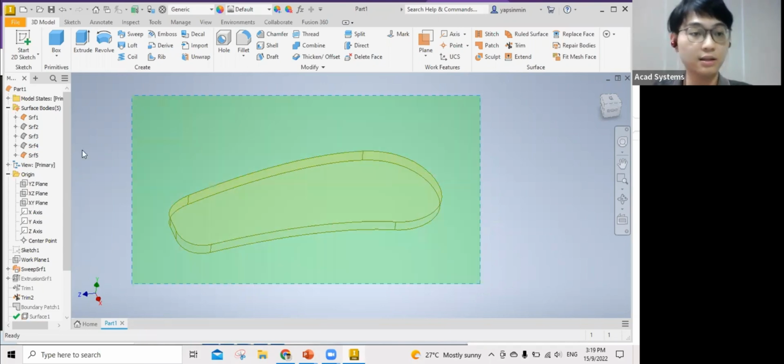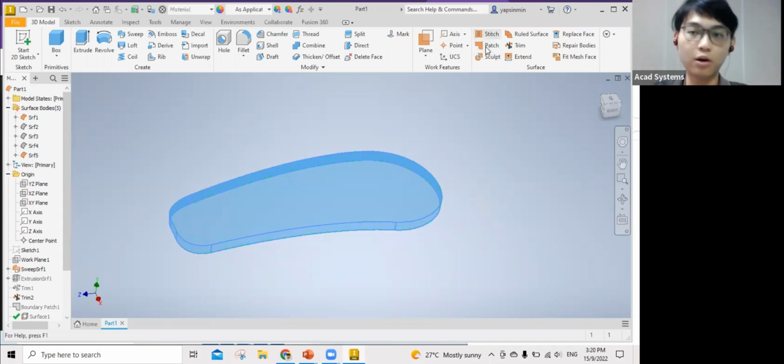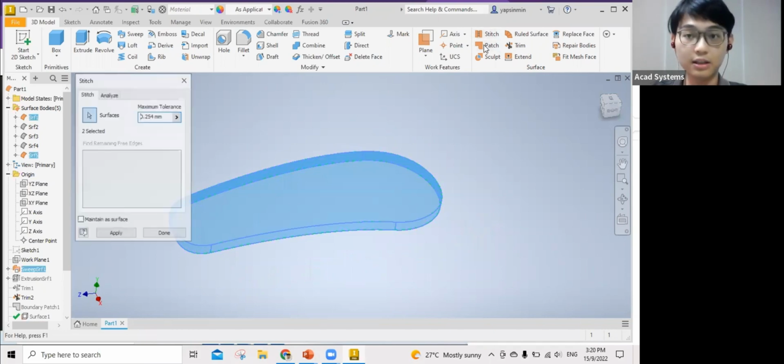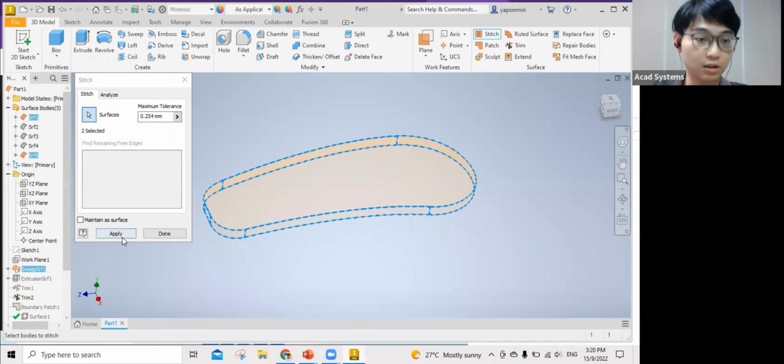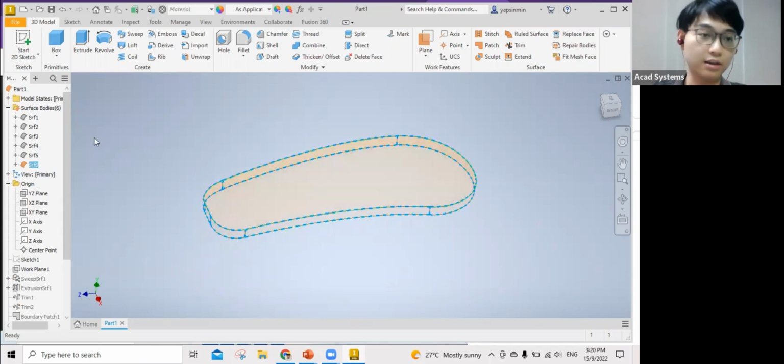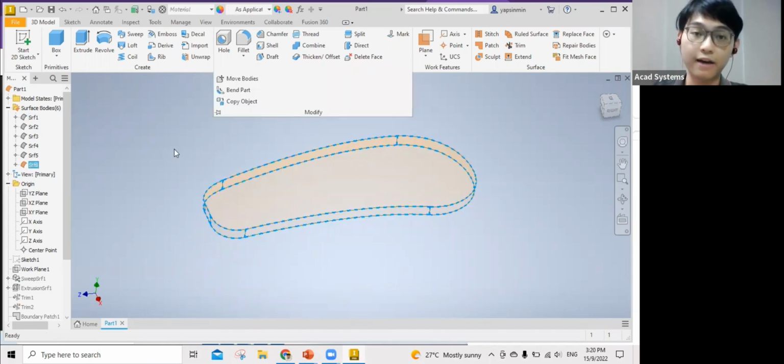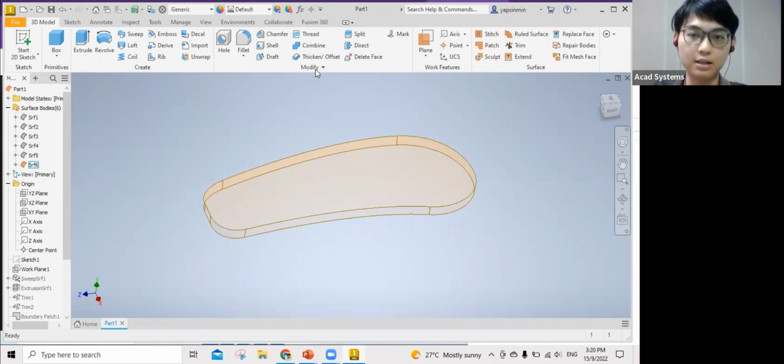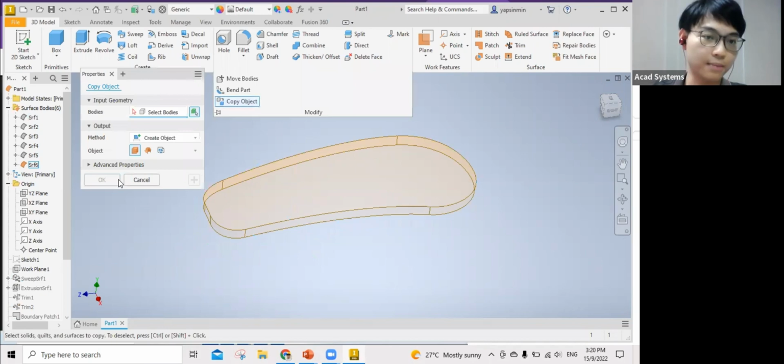Now I'm going to stitch surface 1 and surface 5 into one whole surface. In order to do it, you can use this one. Stitch it. The visible ones are surface 1 and 5, right? So stitch it. I already selected it. So apply. Okay, we are done. So surface 6 is a surface that contains surface 1 and 5, but as one surface. So they automatically become invisible, and I only have surface 6 right now. For surface 6, we're going to have 4 components: left click, right click, bottom, and the scroll. So I'm going to copy this 4 times.